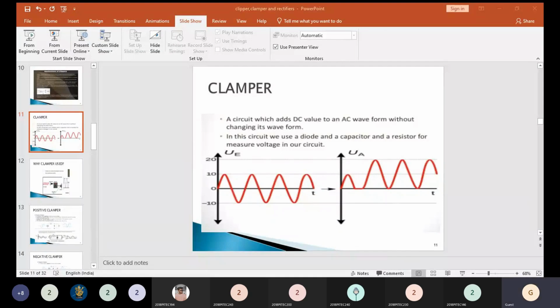For a full wave rectifier, this question falls under the full wave rectifier concept. The 4-diode bridge rectifier is claimed to have the following advantages. You should know the advantages and disadvantages of the bridge rectifier compared with a full wave rectifier with a center-tapped transformer. The first is less expensive transformers, the second smaller size transformers, and the third suitable for high voltage application. Which one is correct? Yes, all three options are correct.